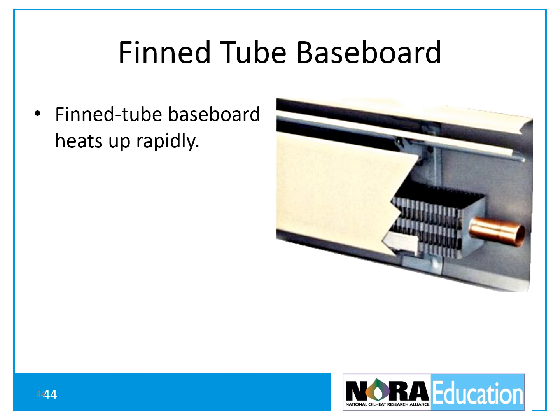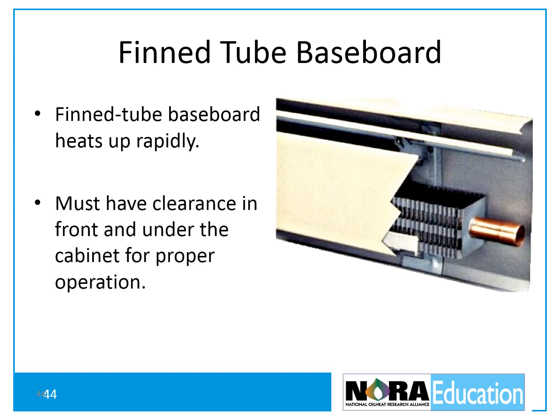Finned tube baseboard typically features copper tubing with aluminum fins attached. It heats up rapidly and dissipates its heat quickly. Clearance in front and proper space under the cabinet are critical for proper operation.